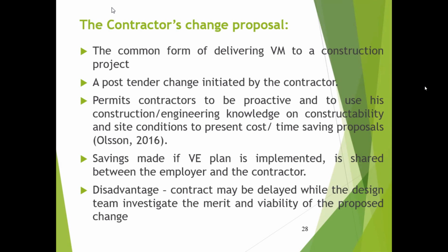And if it is accepted by the client, whatever cost or time saving is reached is shared between the contractor and the client. So this is the most common form of delivering value management to a construction project.